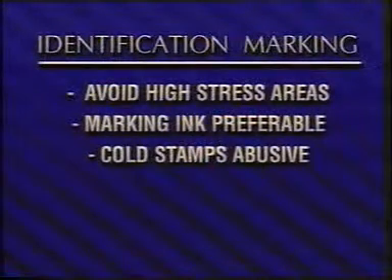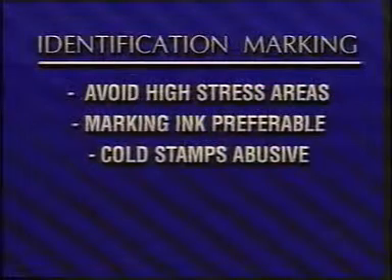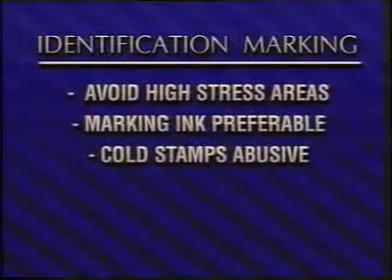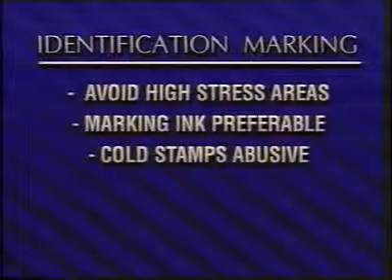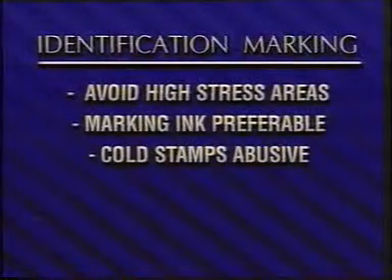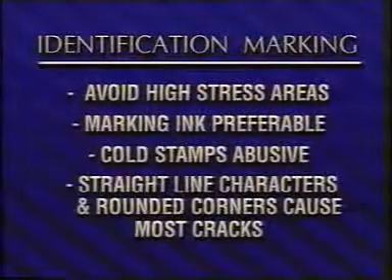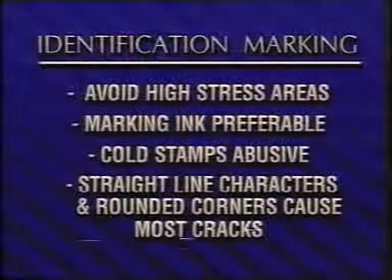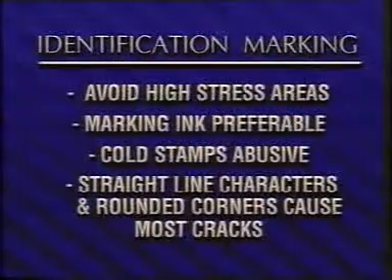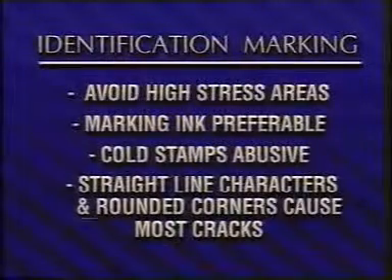However, using steel stamps in a non-stressed area may be preferable to some other type of identification mark in more highly stressed regions. Characters with straight lines tend to cause the most cracks, although characters with rounded corners also cause cracking. If steel stamps must be used, they should be low-stress stamps or dull stamps that will cause the least trouble, particularly if light impressions are made. The stamping should also be located in areas known to be low stress.